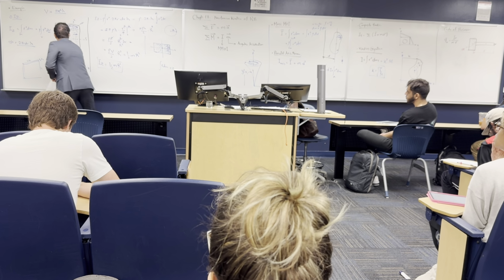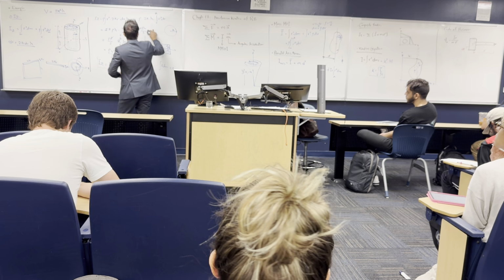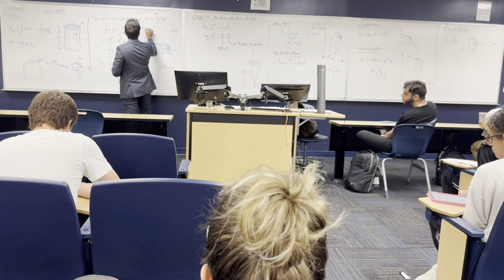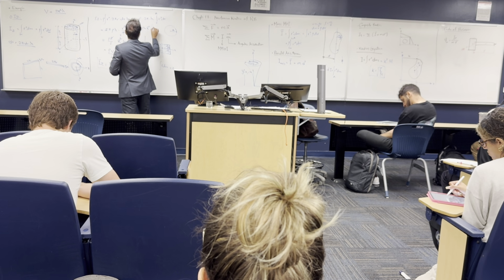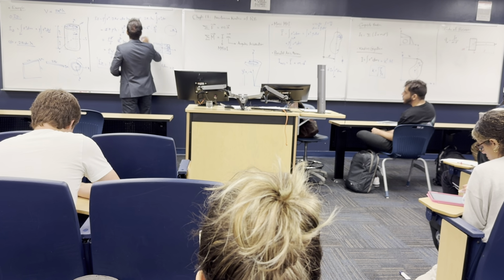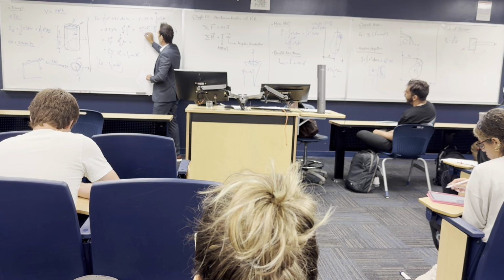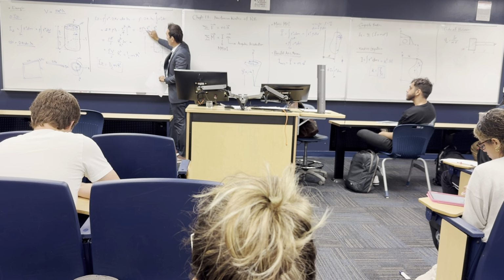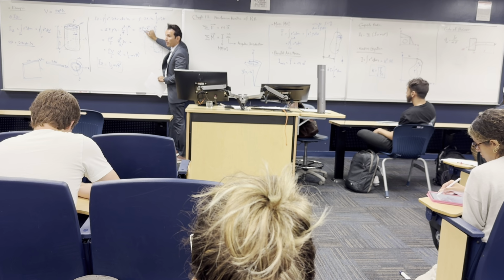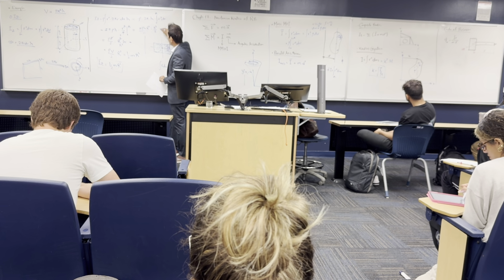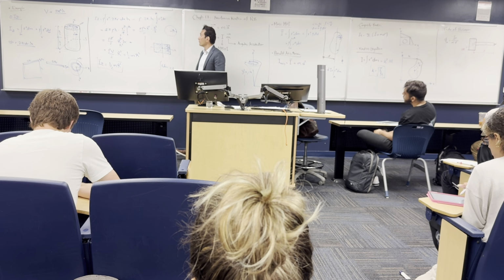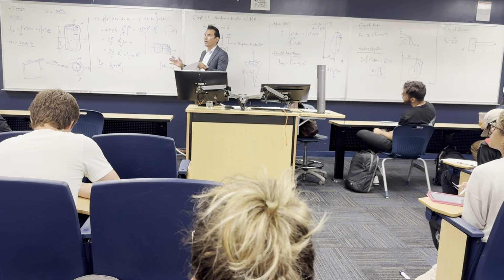And what I did here, I divided the r to the power 4, and I can remove the 2 and put here r squared and put here r squared over 2. This part is the mass because pi r squared multiplied by h is a volume, multiplied by rho is a mass, and this part is r squared over 2. So half m r squared. Okay, so just like separation of variables.